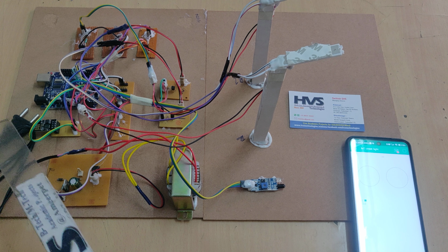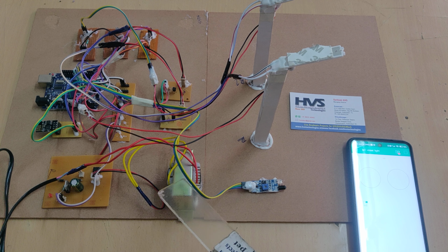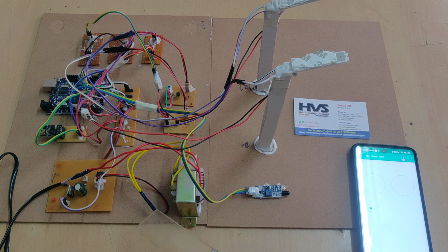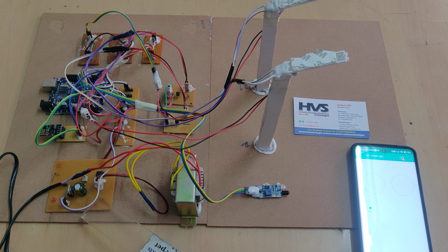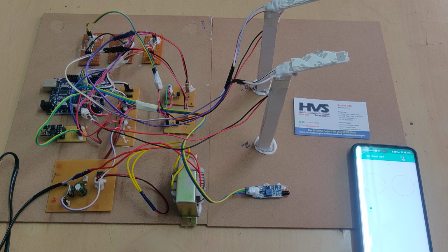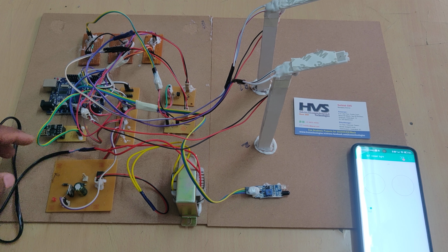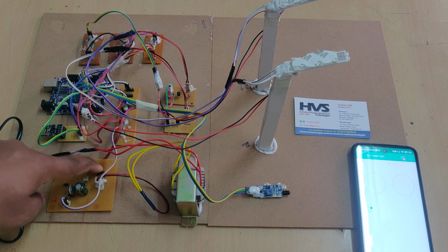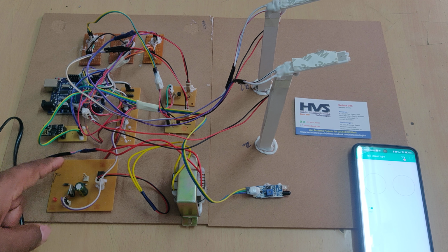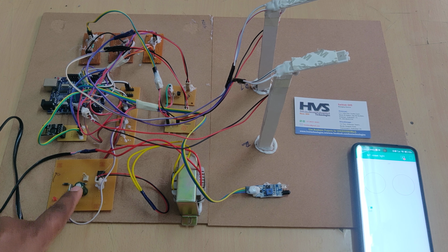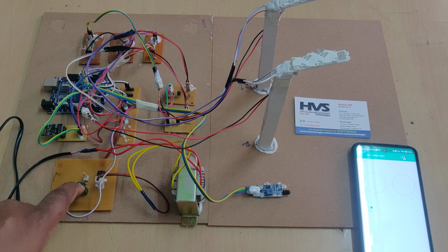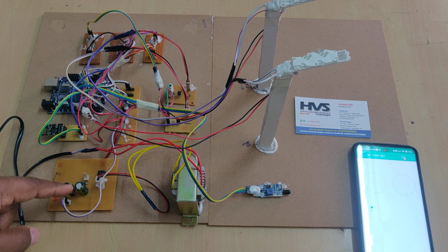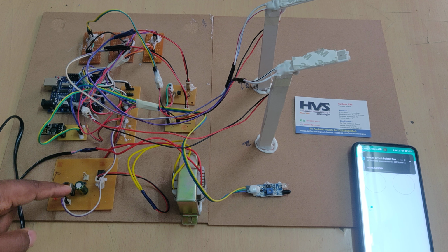And this is the regulated power supply board. Here we are providing 230 volts AC input to the system. This step down transformer will step down the 230 volts AC to 12 volts AC. After this regulated power supply board, we will get the 5 volts DC output. In this regulated power supply board, we have three stages. First, the DB107 rectifier converts the AC to pulsating DC. To remove the pulses, a smoothing capacitor is placed, a 1000 microfarad capacitor. So we will get the 12 volts pure DC voltage, and this regulator will regulate the 12 volts DC to a constant 5 volts DC output.